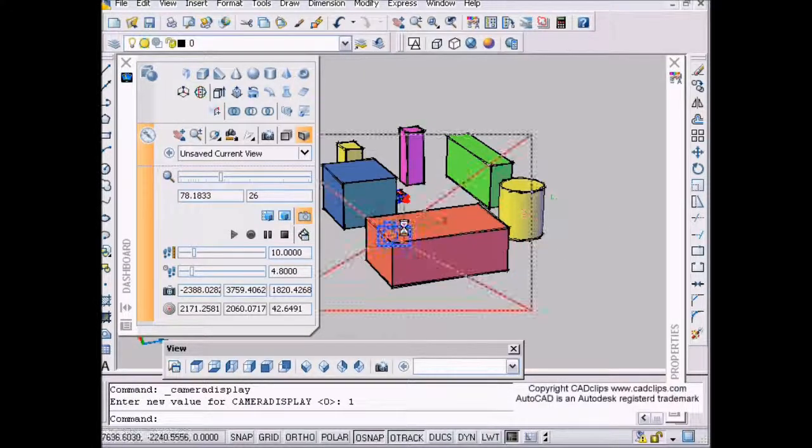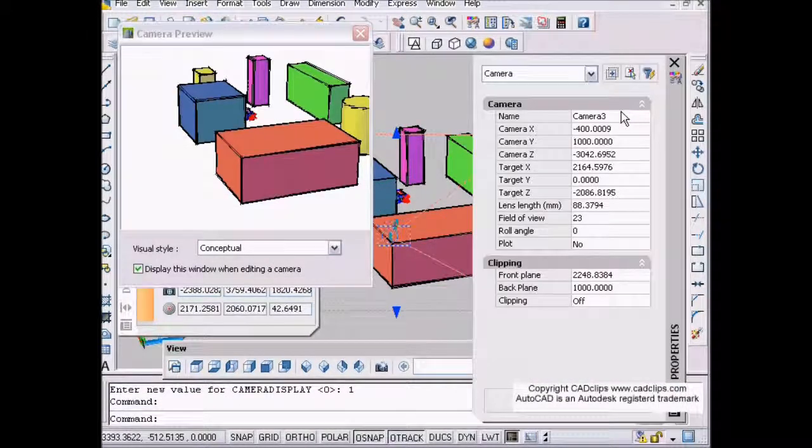Okay, so that's what we can do, and then we can name those cameras accordingly by going back into our paper space, as long as our cameras are turned on, and select that camera, and then check the properties, the name, X, Y, and Z. Mainly it's the Z's you want to be able to change inside of here. Okay, and I believe it looks like it's relative to the UCS or something inside of here.